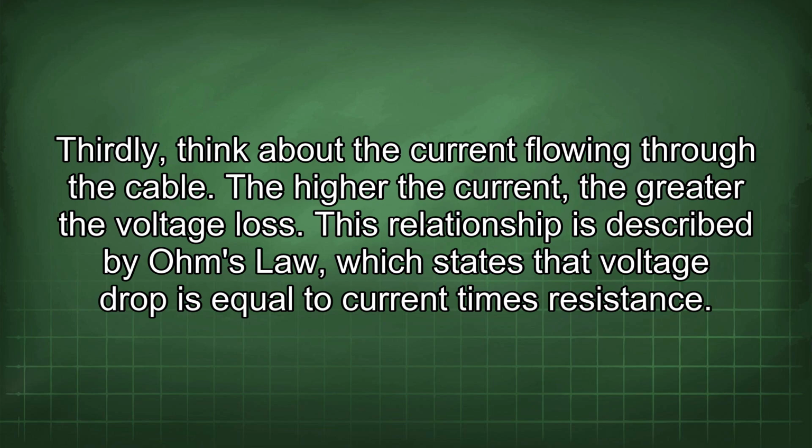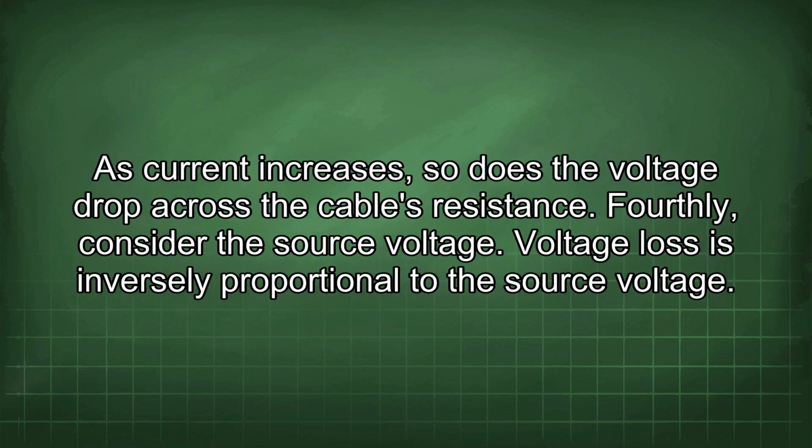Thirdly, think about the current flowing through the cable. The higher the current, the greater the voltage loss. This relationship is described by Ohm's law, which states that voltage drop is equal to current times resistance. As current increases, so does the voltage drop across the cable's resistance.